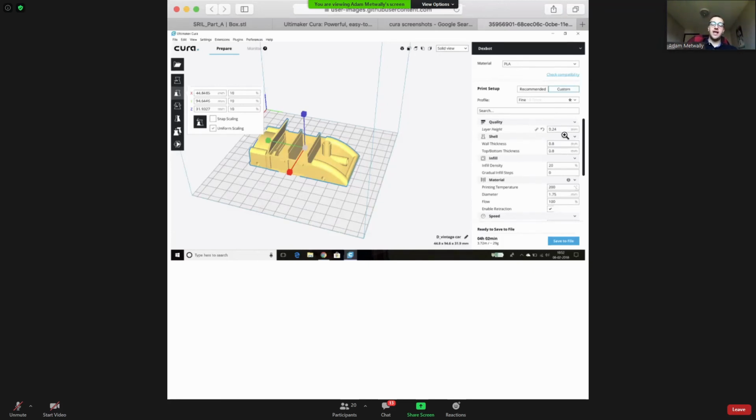So in FDM, you have these plastic layers, so you can make those smaller or larger. Obviously having smaller layers or more layers is going to make it a better quality part. Whereas having only a couple layers, the separation between them is going to be very large, so it's going to be a less dense part.